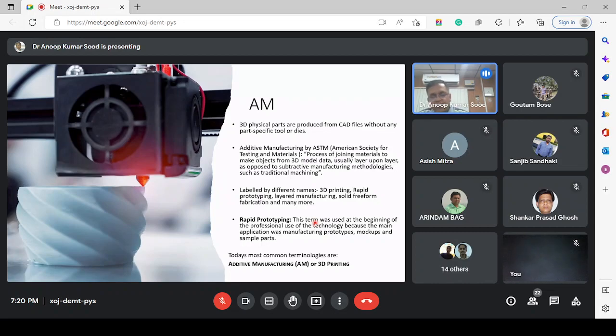So this way I have generated one layer. Now above this layer, if I deposit another profile matching that layer's constraint, in this way I will be able to grow the entire 3D part. Additive manufacturing is also based on the same principle. In this principle, we have a robotic arm which will move. That robotic arm may be carrying an extruding material or maybe a power source, and it will move as per the layer profile requirement and generate a layer profile. This profile is generated over a table, and when this table moves downward, the next layer will be generated over that. In this manner, we are able to consolidate these layers one above each other and get a 3D structure.